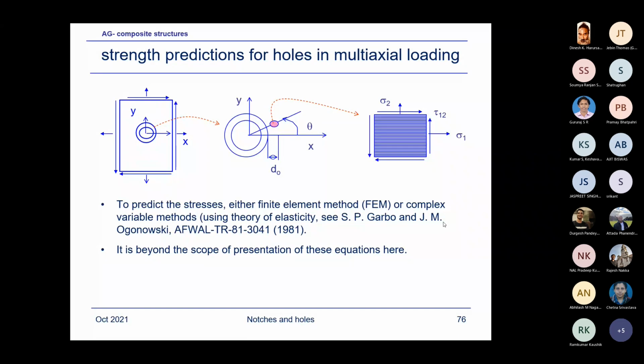Of course, here you don't need the characteristic dimension for the bolt hole. Here you will need filled hole tension, and filled hole compression you can forget over here. Filled hole tension, open hole tension, and then you can use bending also for the bending load.